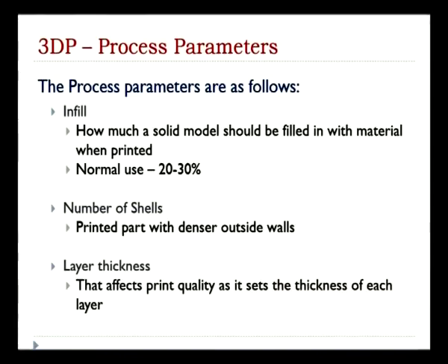Say, for example, I'm building a process. In some areas where I really don't need material, I can leave it as an empty space, right? But in some special cases, I need a very solid, rigid structure. In that case, I need to use this material. Normally, for this infill, if the material doesn't need additional specification, we can fill it 20 to 30%. That is fine enough.